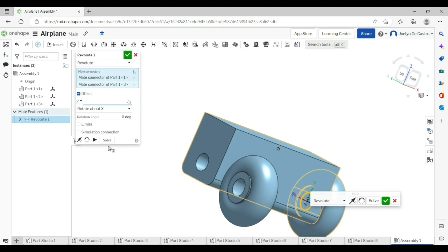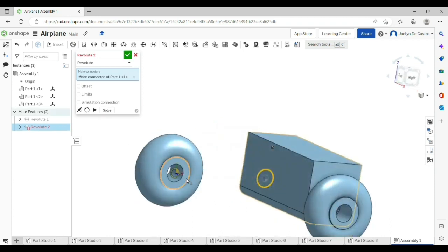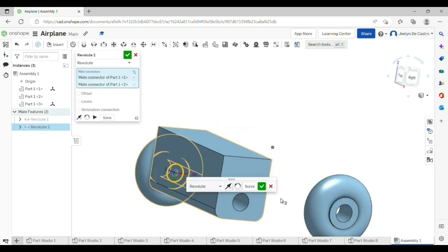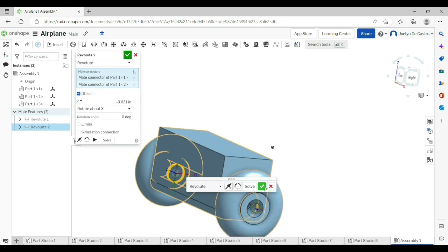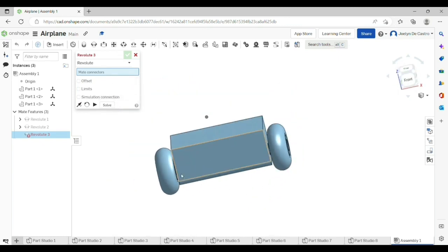Also, click on the wheel and place 2 wheels on the assembly window. Then close the Insert menu. So in this case, we're going to assemble these items. Next, we're going to mate the wheels to the wheel block using a revolute mate to be able to turn. Set the first mate at the end of the axle hole in the wheel block. Make sure we have that axle hole itself and click for the first mate.